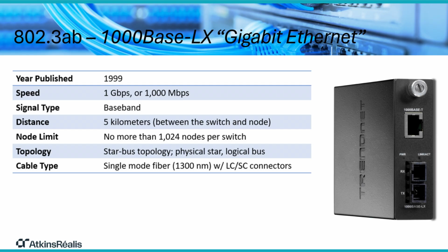And that immense reach is what lets the RTMC connect to a controller at a distant intersection or a sensor site way down the road. It's what makes the whole system work over a large area. So really, the backbone of any current system requires everything to be speaking that 10/100/1000 auto-negotiation language to keep things running smoothly. It's non-negotiable. Understanding why you use a star or a mesh over a bus or a ring, and knowing how Ethernet manages traffic, those are the foundational concepts.